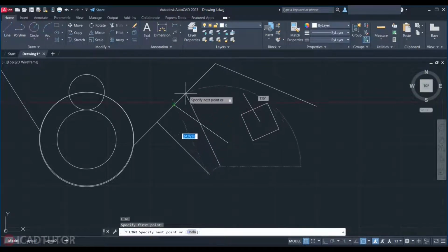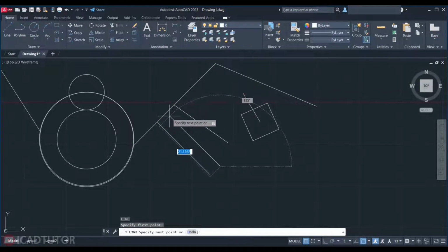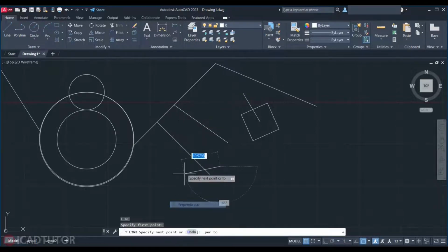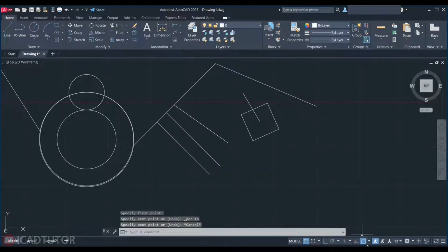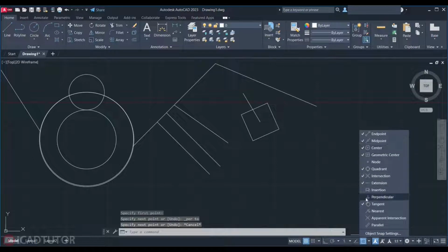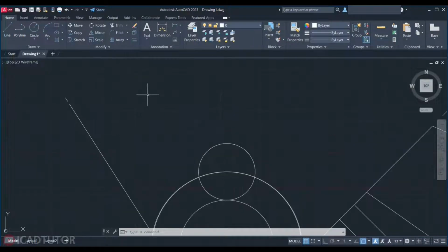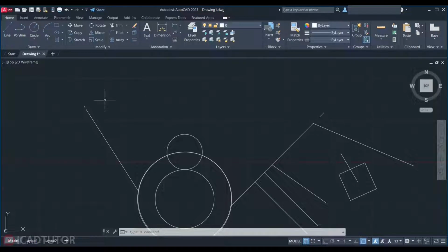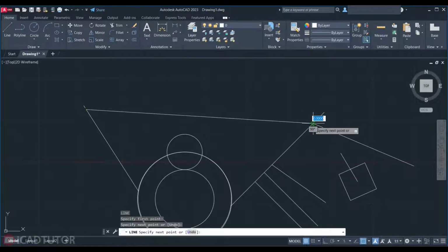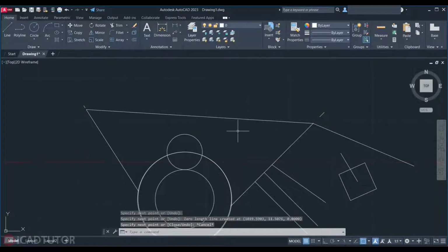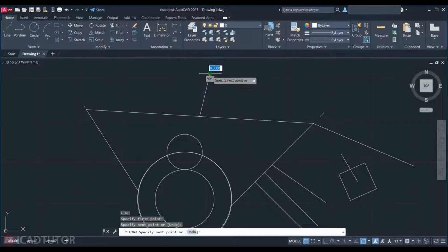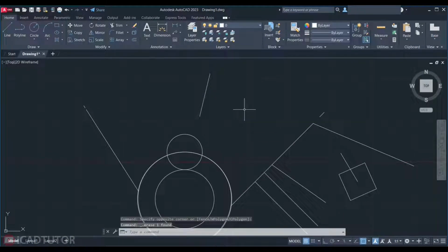Look, if you wanna draw another line, the perpendicular sign doesn't appear. So hold down shift key, right click, perpendicular. Or you can tick the perpendicular option to use in other commands. Okay. The last point that you may need to know. Here I want to find the center of these 2 points and draw a line using the center point. So I draw a line between these 2 points. And now using the midpoint I can draw another line. At the end, delete this line.